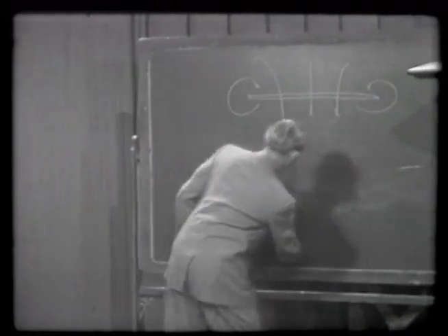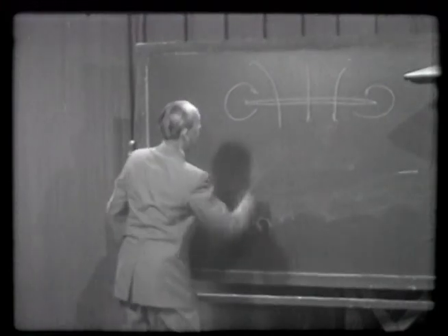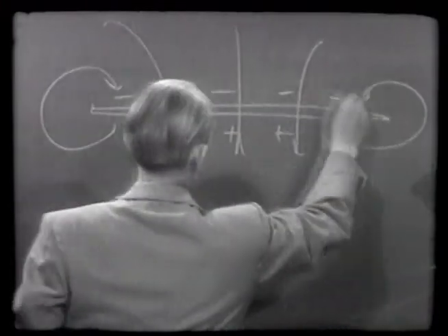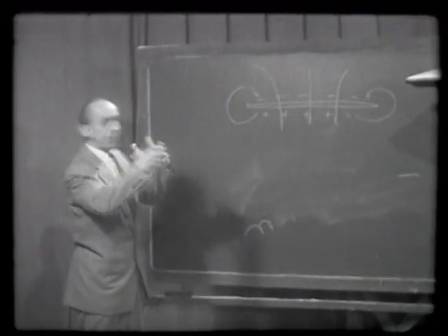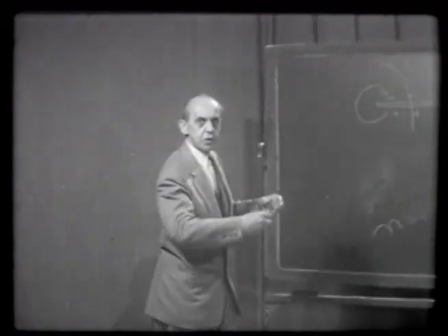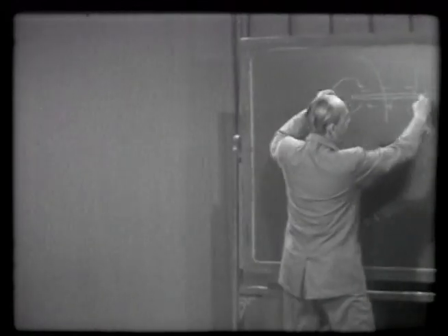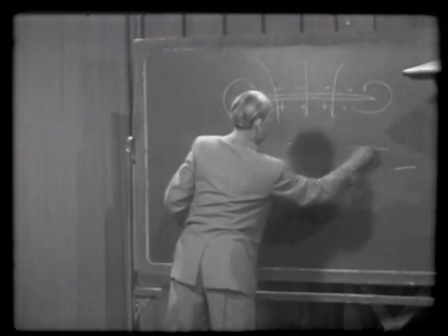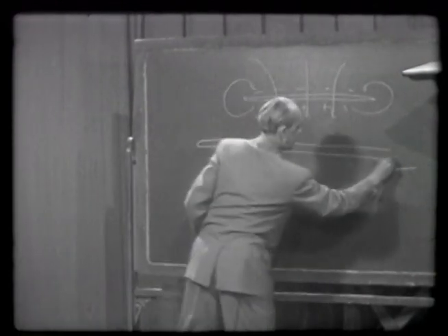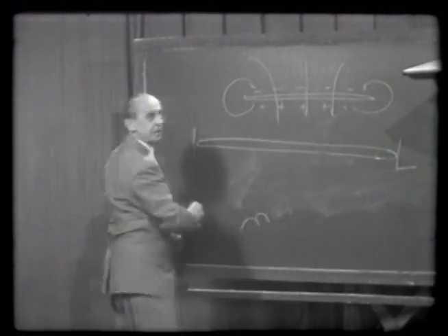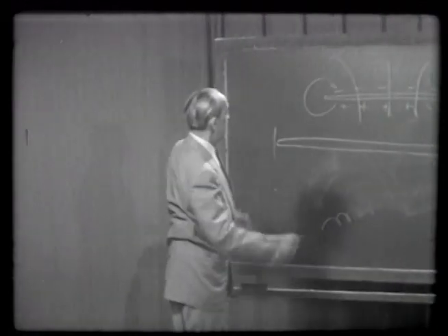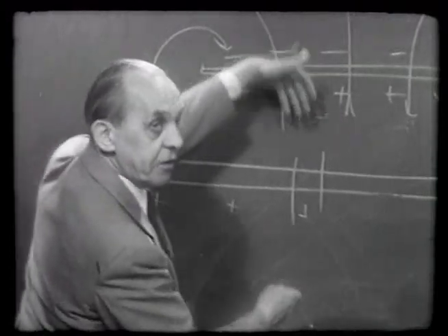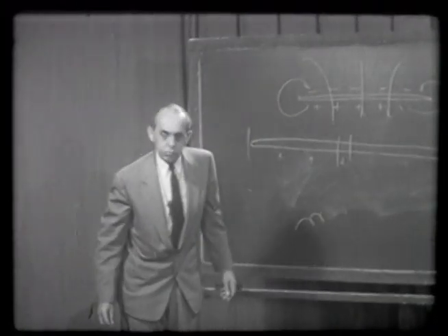We have, as we said, underneath the wing, the higher pressure, above the wing, the lower pressure. If we would distribute the load on the wing over a larger distance, a larger span, we call this distance from one tip to the other tip the span of the wing, then certainly the pressure differential across a certain section will be smaller.